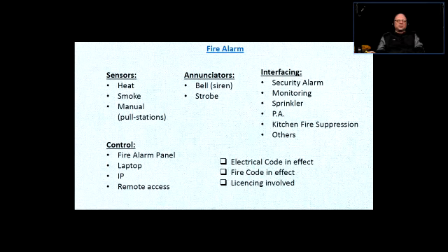But usually the pressure goes down below a certain level if one of the sprinklers is triggered. How do you trigger a sprinkler head? Well, if there is a fire, the heat that is present is going to melt that little trigger sensor in the sprinkler head, and that thing is going to break and release the water.